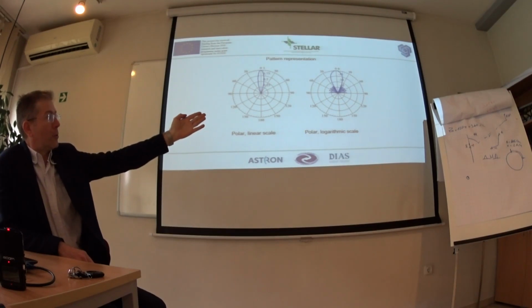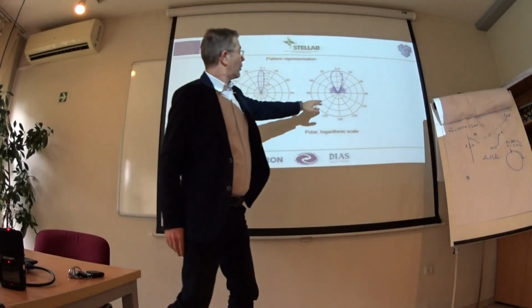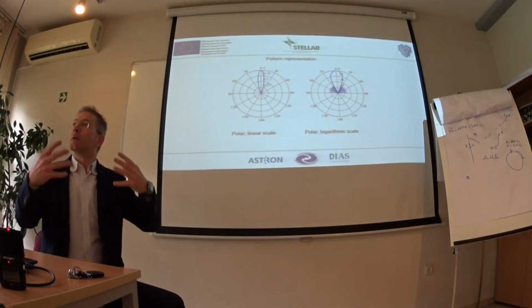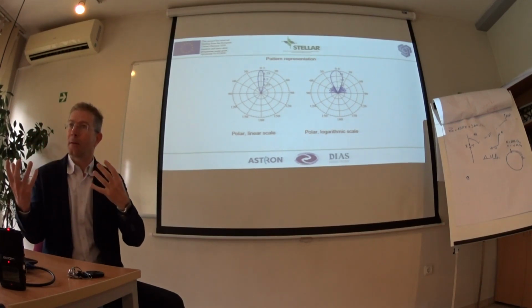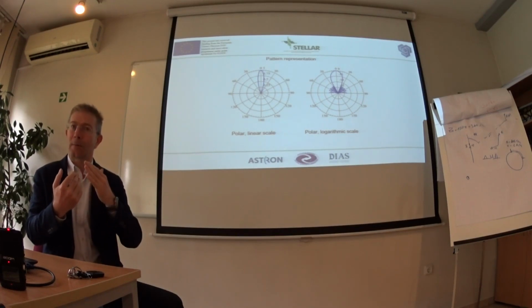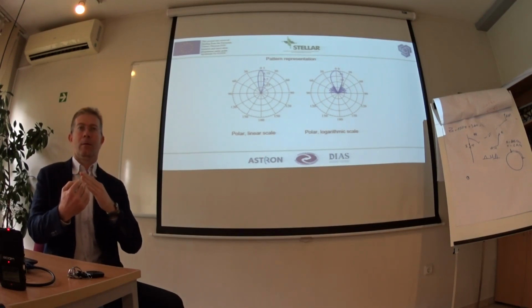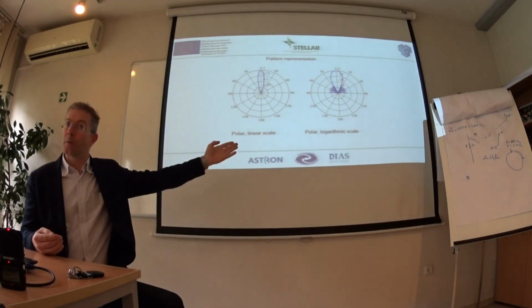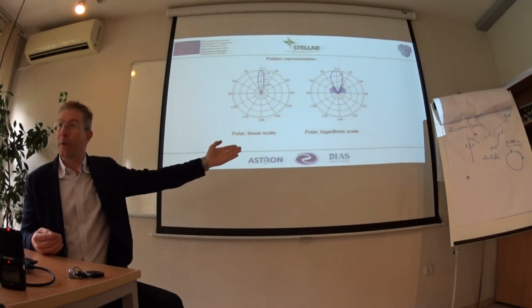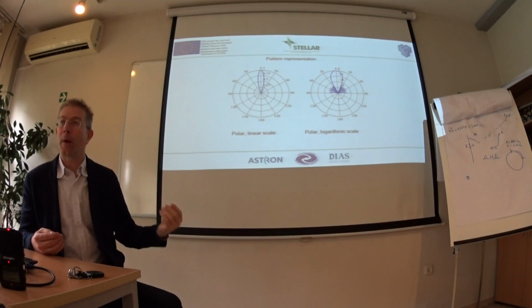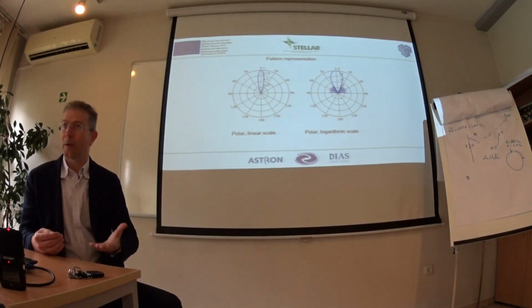And we see that in logarithmic scale, on a level minus 40 decibels, actually there are things that radiate emissions, but since they are 10,000 times less than the main radiation, main emission, they are not noticeable in a linear scale. But most of the equipment works with logarithmic amplifiers for small signals. So these small radiations are quite noticeable with instrumentation.